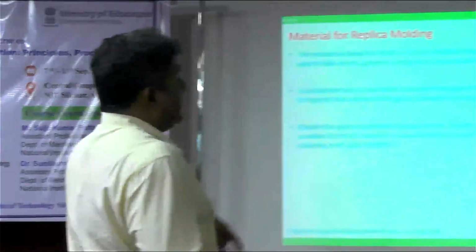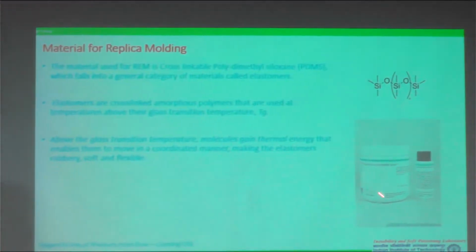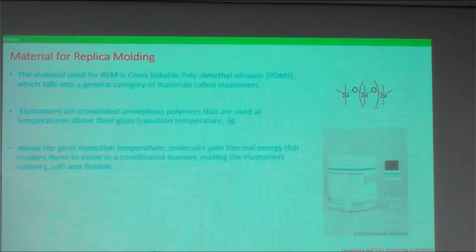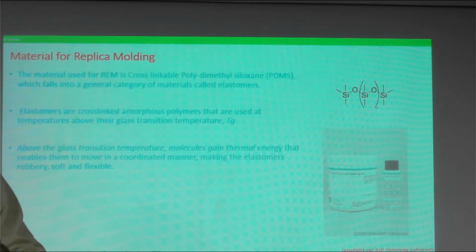Now, coming back to this particular material, what we have here is an oligomer, which is a high viscosity liquid, and the crosslinker. And what you do, you mix them and you put it for thermal annealing. So you just cure them at 120 degrees centigrade, 4 hours or 6 hours. And what happens? During this thermal annealing, the crosslinks grow between the adjacent chains, resulting in a crosslinked network, right?